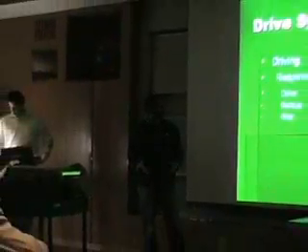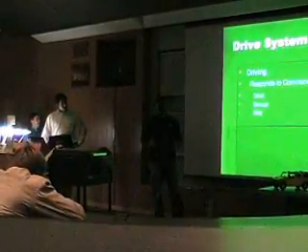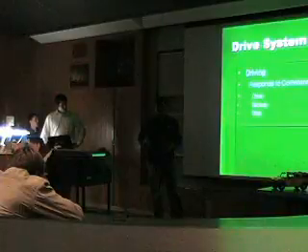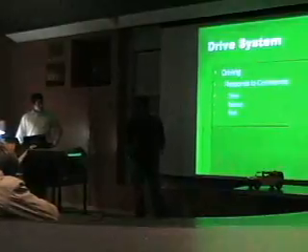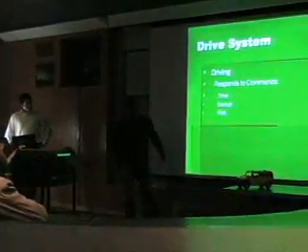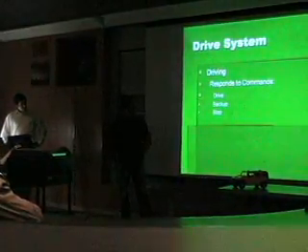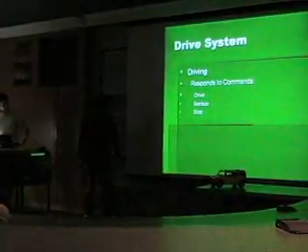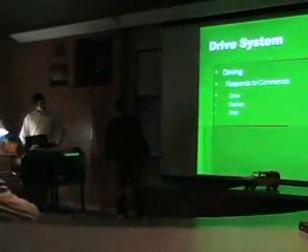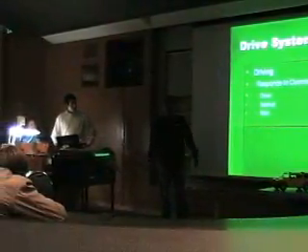So when drive forward is commanded, it comes from the user to be interpreted in the same way in the PIC. The PIC signals 5 volts to one of the H bridge terminals and 0 volts to the other. So that H bridge also turns the switch of the 9.6 volts to drive the motor in the corresponding direction. Back up works in the same way. During stop, most terminals will be off.